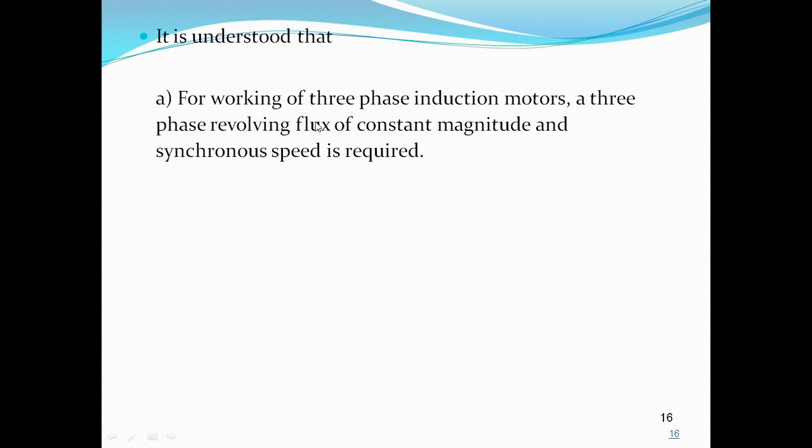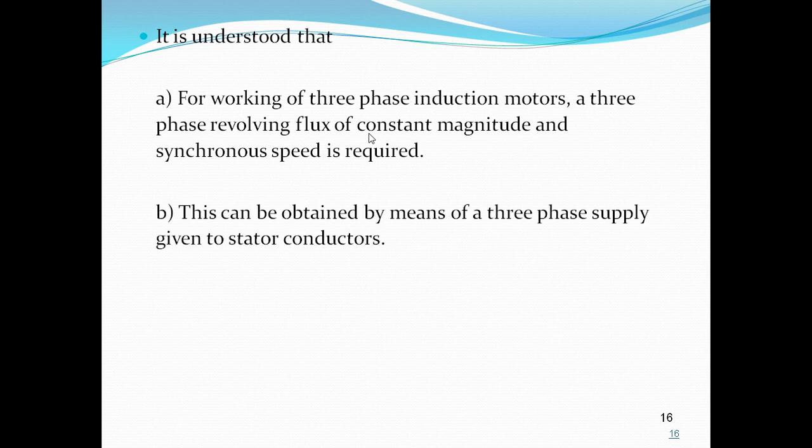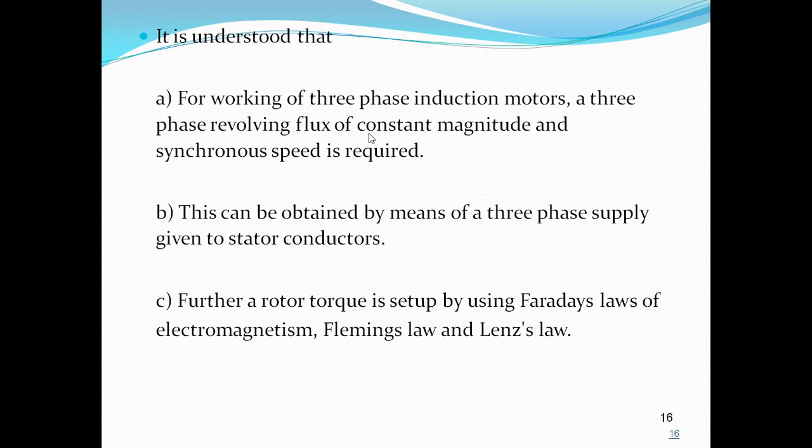So for working of a three-phase induction motor, a three-phase revolving flux of constant magnitude and synchronous speed is required. This can be obtained by means of a three-phase supply given to the stator conductors.